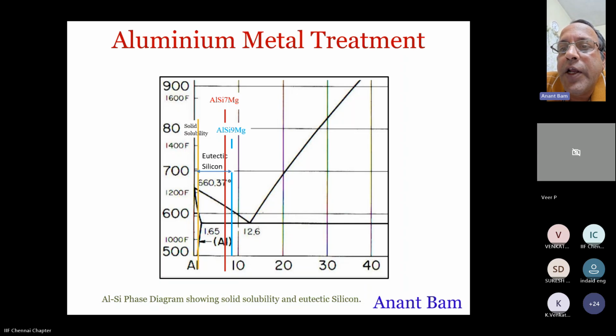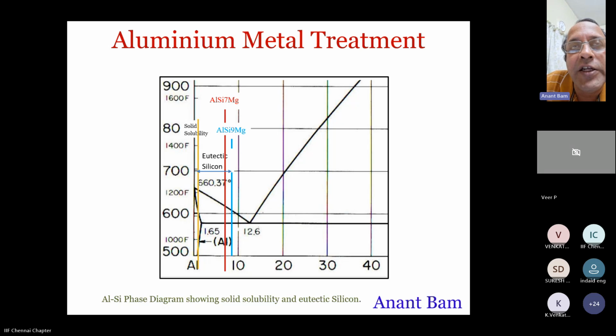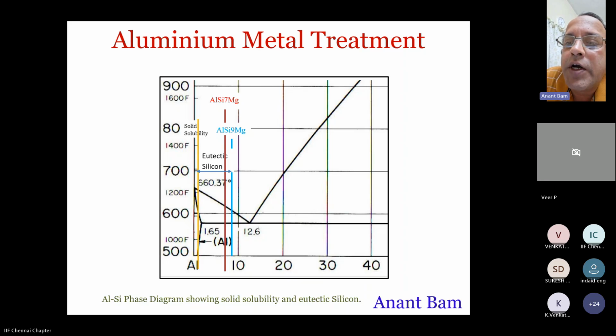That is between the liquidus, the intersection of the red line with the upper side of the V, and the solidus, the intersection of the red line with the horizontal line. In this freezing range, one by one, these alpha particles will form. And just above the solidus, 50% of the aluminum alloy will already be solidified.